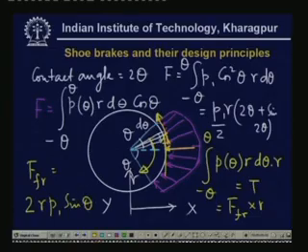Now what we see is that the normal force is F, the total frictional force is Fr, and of course, we have forgotten this important thing, mu. So therefore this is twice mu times r P1 sine theta. We must remember that the total friction force is mu times this force acting over here, dP. This is the friction, this is the total force on this area, and the frictional force is mu times that.